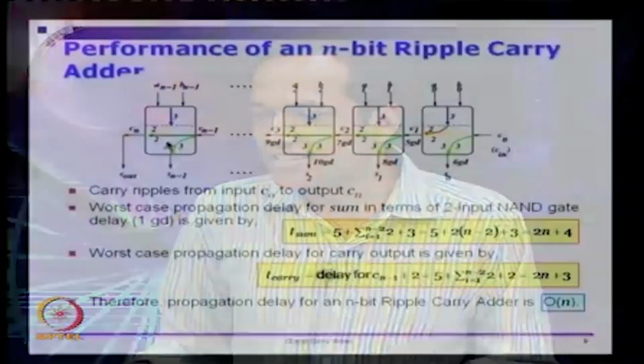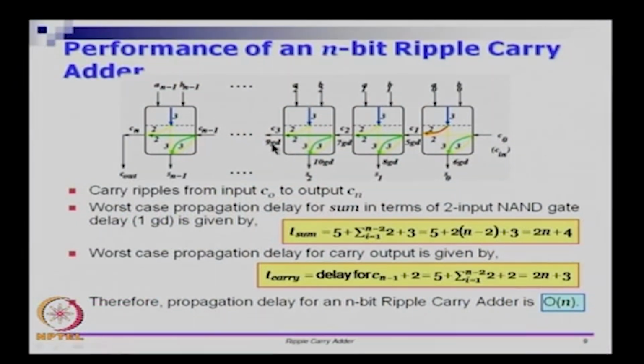So one final thing that I want you to think about is the carry that is coming out here, right, has an interesting property. If I have a 4 bit ripple carry adder and let us say I have another 4 bit ripple carry adder, I can take the carry out that is coming from one stage and give it as C0 for the next stage, you can make an 8 bit adder out of that, right. You can take 2 n bit adders and attach them back to back and you can get a 2n bit adder. So that is a very interesting property of ripple carry adder. This is one of the few circuits where you can take two circuits and put them together, and without doing any extra work you can actually get a bigger operation done.